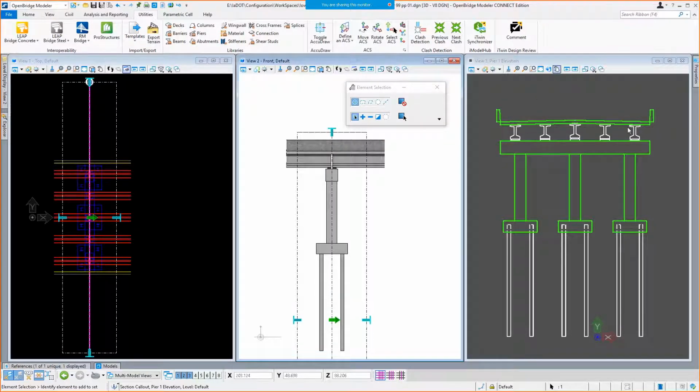So I could change, let's say, the girder spacing. I could add girders. I could take girders away. I could go to a completely different girder. If I want to go from a 54-inch girder to a 63-inch girder, I can do that in the LEAP, like LEAP Concrete. Or if I need to change the thickness of a flange or a web or something on a steel girder bridge, I can do that while I'm sitting in the analytical product and then rerun my analysis.